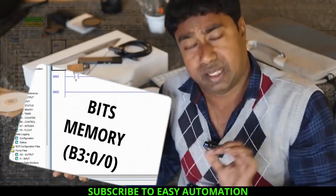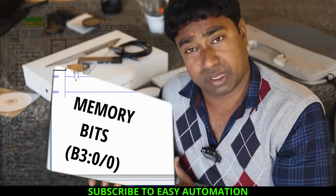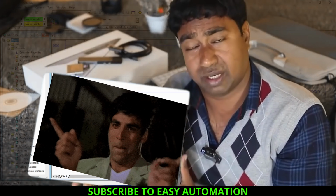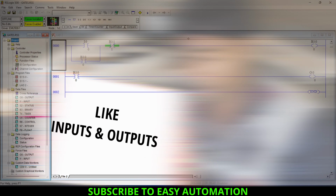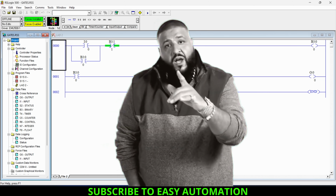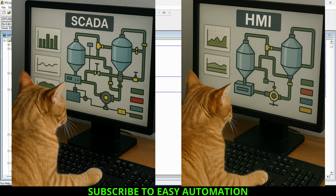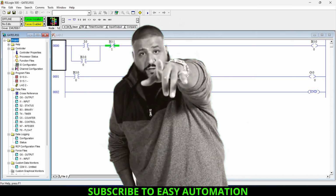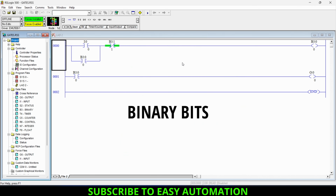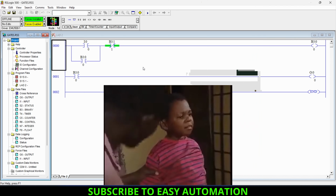So the bit memory or the memory bit is the binary bit which can be used for temporary addressing of any instructions like input and output, and it can be used for triggering instructions as well. But mostly memory bits are used whenever there is involvement of SCADA or HMI in the overall program logic. So if you want your program to be more optimal, then these bits will be more useful in those cases. So now let's get some idea how we can use these memory bits.